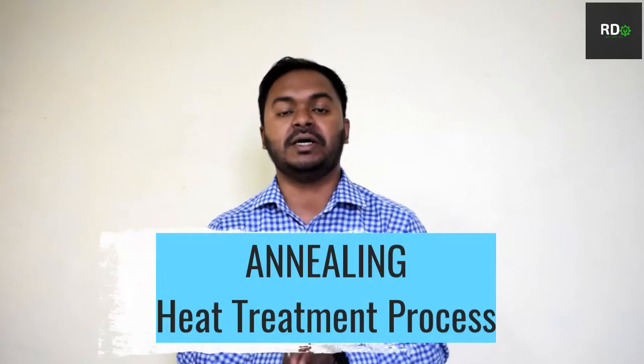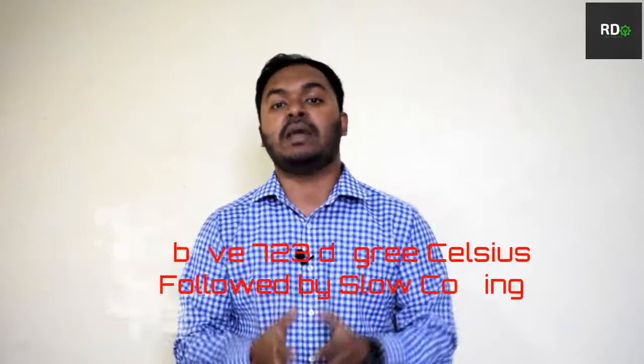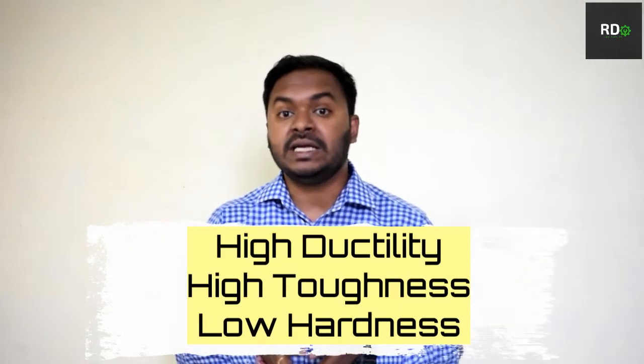I am Rathin Datta. Today we will be discussing the heat treatment process, and mainly the annealing heat treatment process. In annealing, we subject the material to a high temperature that is above the critical temperature. In the case of steel, it is more than 723 degrees Celsius, followed by slow cooling to room temperature, and the result is that the microstructure shows high ductility, high toughness but low hardness.